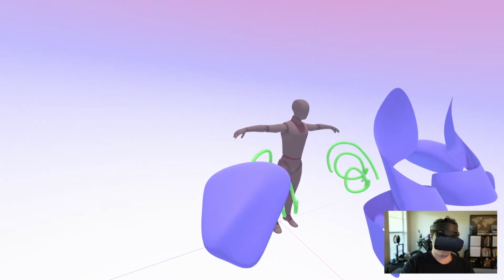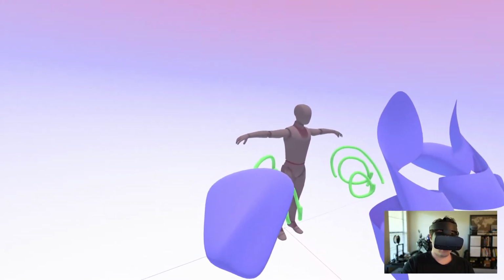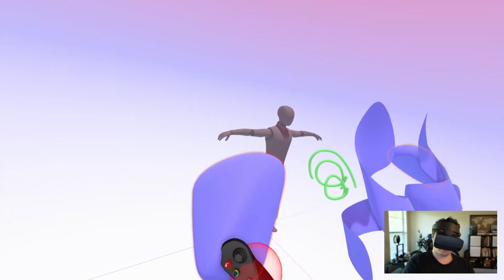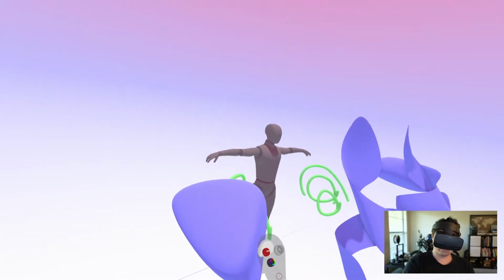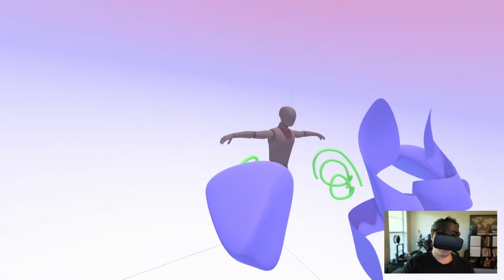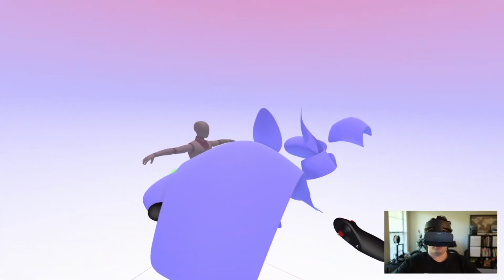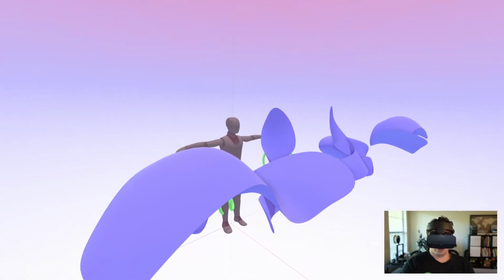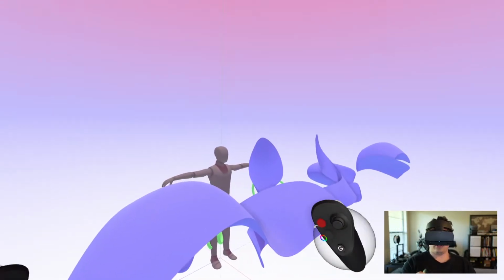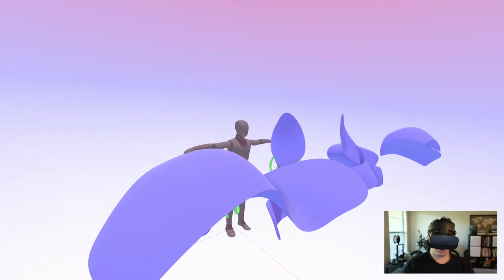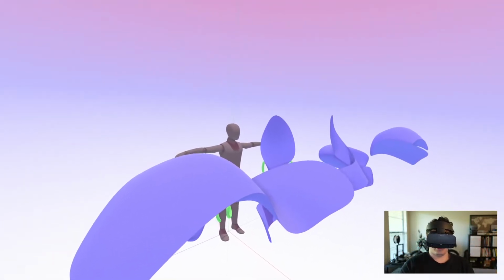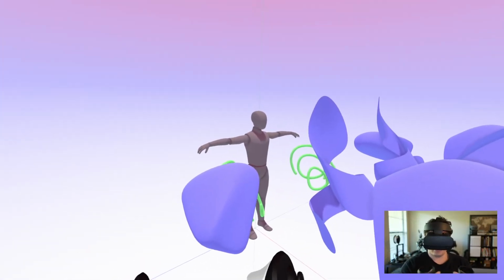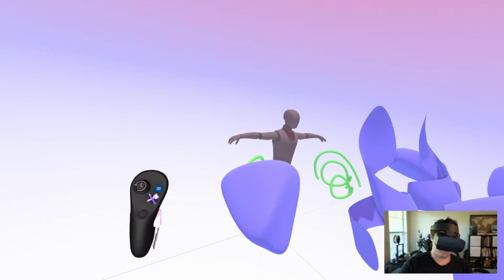or some other program like that, you'll notice that it starts to look weird, like it starts to render weird, or it looks like it's inside out. That's because when you drew it, the normals were on one side, and the outside, quote unquote, of the surface was actually inside, and you kind of folded everything in, basically, if that makes any sense.